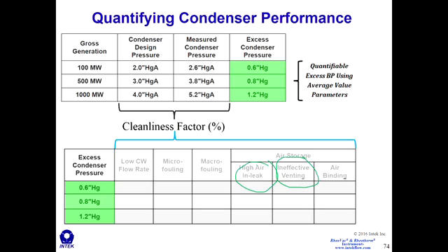If your equipment is LRVPs, then a damaged impeller or high seal water temperature will decrease air offtake flow rate from the condenser, and that will cause condenser pressure to increase. If the vacuum equipment is steam jets, then perhaps low motive steam pressure or high intercondenser pressure on the discharge of your steam jets are causes for lower air offtake flow rate from the condenser, and that also can increase condenser pressure.